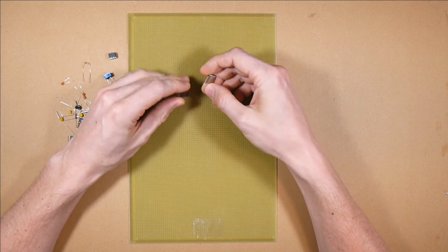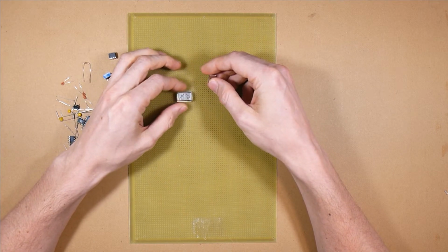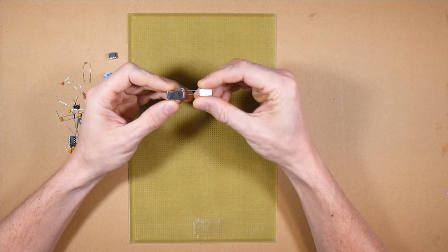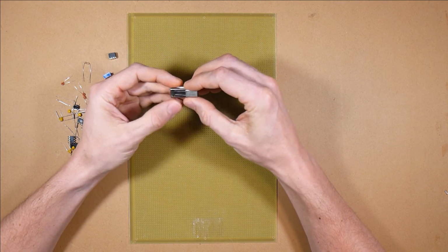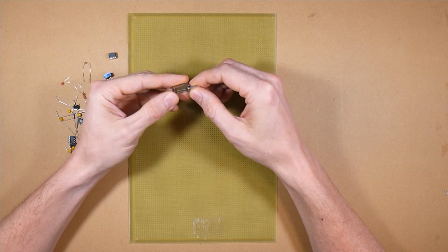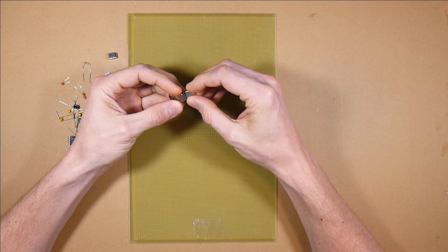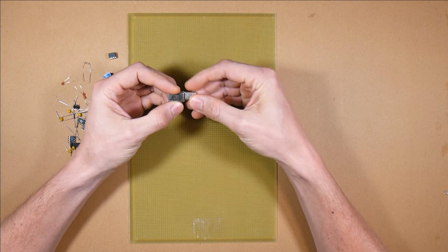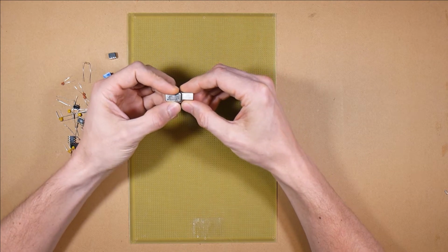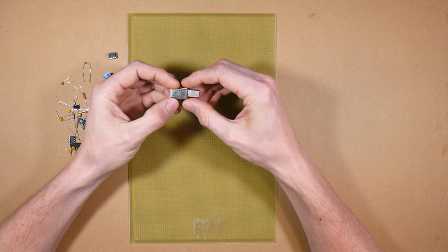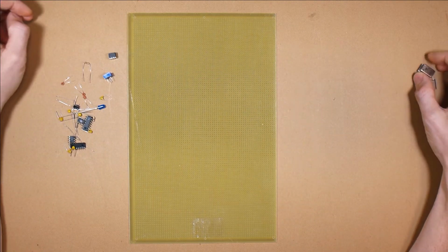And we will not be using this on our build because they are just too fast. This one is a 50 megahertz and this one a 10 megahertz oscillator, and we don't want that. We want a much slower clock pulse, so we'll be able to see what's going on. So we need a million times slower than this one. So we don't need a megahertz, we need just the hertz.